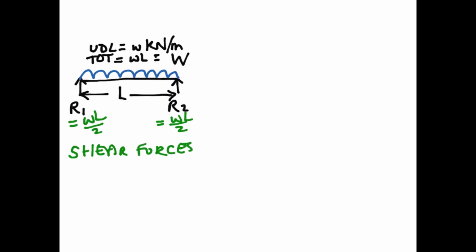Okay, and strictly speaking, we don't need to talk about shear forces here because we have a simple exercise. But when you get to more complicated load arrangements to look at, there's a really useful part for shear known as the point of zero shear, which you can use to determine where your maximum bending moment occurs. We do use that later in this lesson when we're combining lots of various load cases. So let's put that UDL back on,